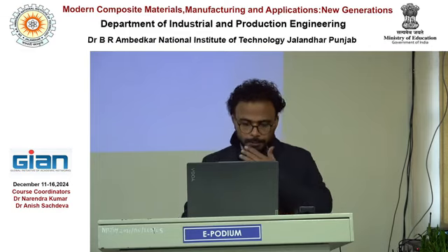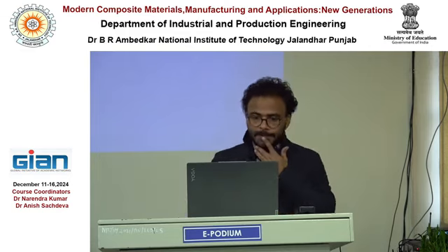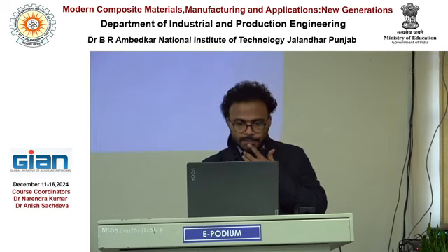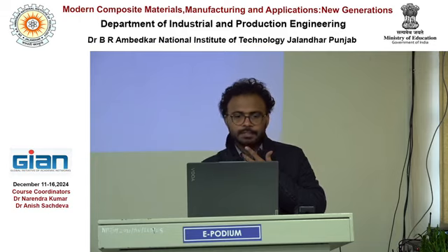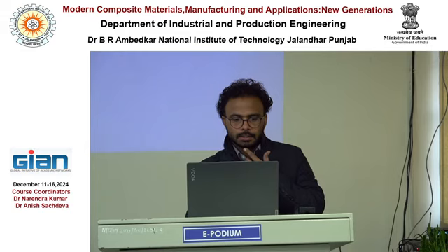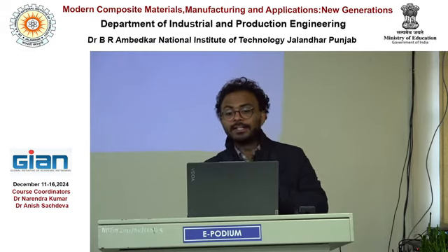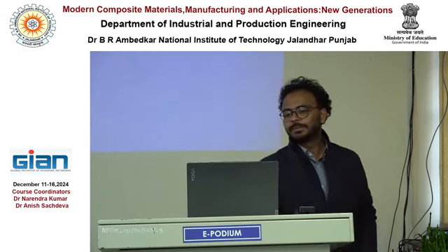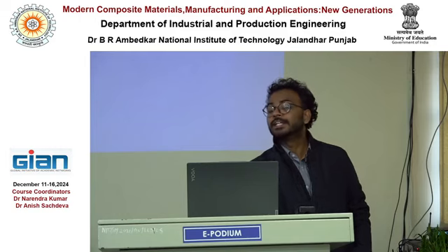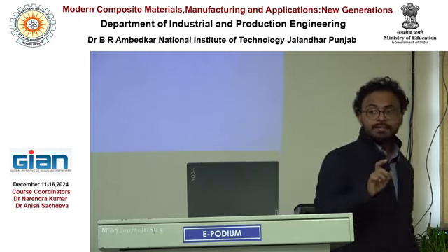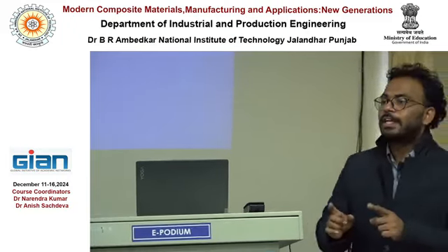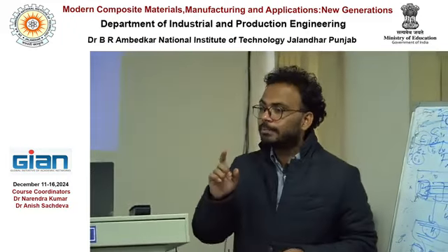Not DLOAD. UEL. You can search here for the subroutine name. Assigning thickness to cell faces. You are changing the modulus variation with thickness, right? Here you can get some solution, but it can be done. USDFLD. Okay, this one, you can go through this. USDFLD, that means user-defined according to field. So USDFLD is a subroutine you can work with. Okay, the name is USDFLD.